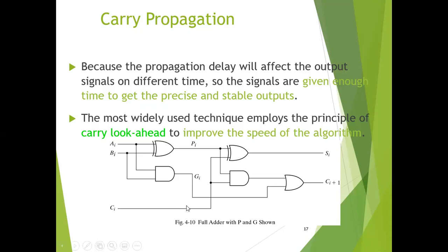And we can see the most widely used technique employs the principle of carry look ahead to improve the speed of the algorithm. That carry look ahead we have also used to make the full adder by using two half adders. This is the full adder with P and G shown as the propagation outputs of the given gates. We can find and calculate the number of gate levels for carry propagation, that is, how many gates and how many stages are used to construct a system.